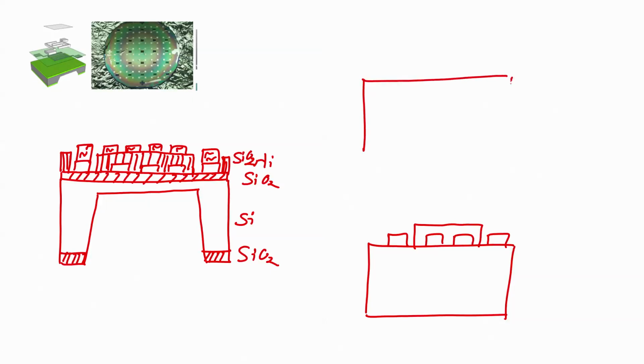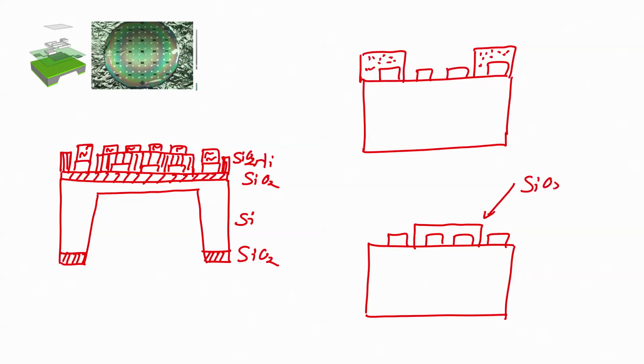I take the wafer with my aluminum interdigitated electrodes, and I coat the photoresist in such a way that it will cover only these two electrodes. This is my photoresist. What I want is silicon dioxide and aluminum. So, let us have aluminum like this, it is easy to keep the pattern same, right.